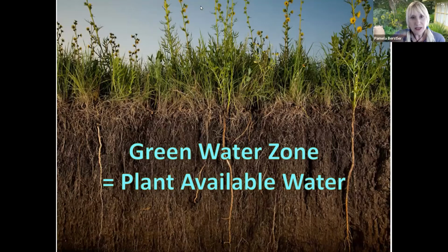Well, imagine if we could start growing landscapes that had root depths like the ones that we were seeing on the prairie, those 15-foot root depths. I mean, heck, just get me to 2 feet, 3 feet. And imagine that plant available water is enormous, right? Think about the calculation, your total irrigation runtime. Actually, you wouldn't even get the total irrigation runtime. You would see allowable depletion of 3 feet and be like, I don't think this thing has to be irrigated, right?